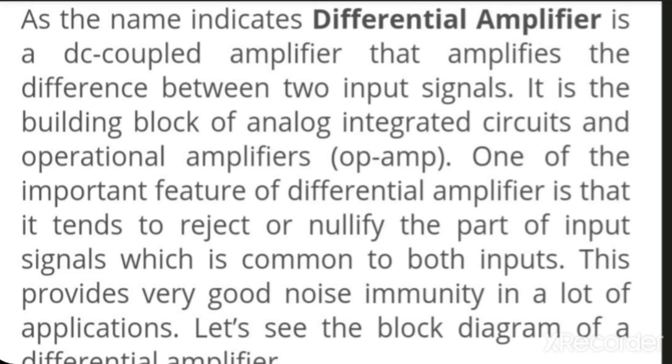Differential amplifier is the basic building block of operational amplifiers. Hence, it is necessary to analyze differential amplifiers to understand the operation of operational amplifier. As the name indicates, differential amplifier is a DC coupled amplifier that amplifies the difference between two input signals. It is the building block of analog integrated circuits and operational amplifiers. In short, operational amplifiers are called op-amp.